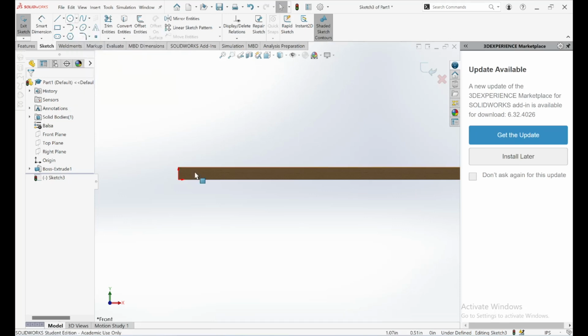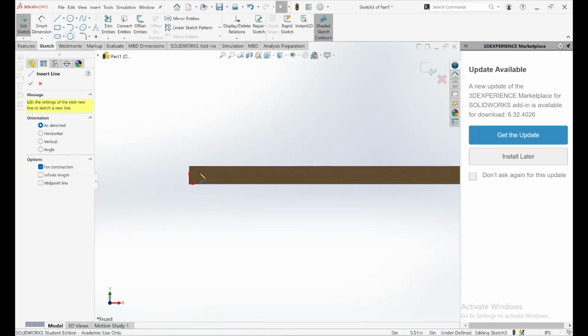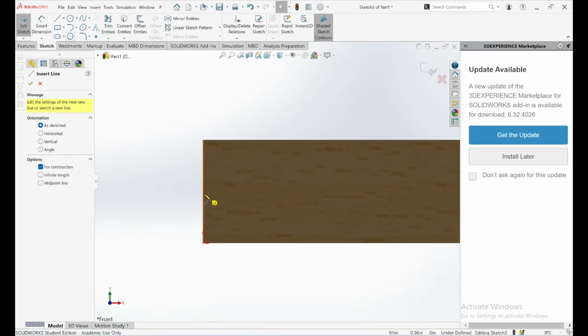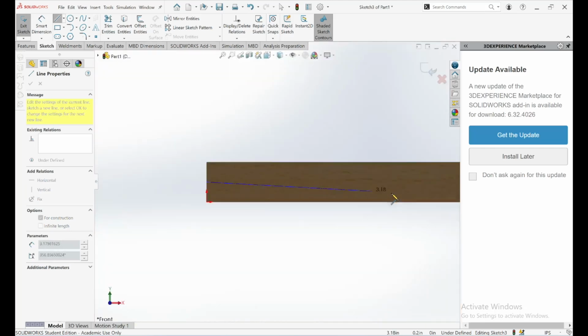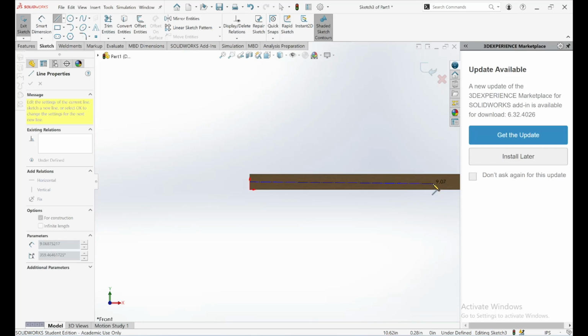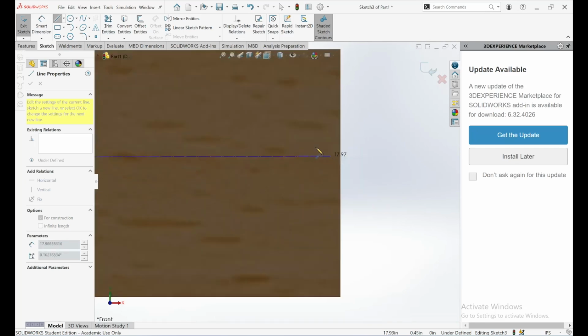So let's go up into circle. Or actually, let's go into center line. We're going to create a center line across this beam. Let's go down to midpoint. Let's find this midpoint. This midpoint is going to be where it highlights orange. SolidWorks is really great with trying to snap in different constraints automatically, especially midpoints. So you just want to hover to look for that midpoint and then select it on this other edge here. Found it right here.